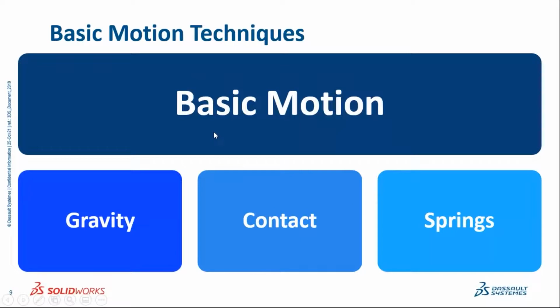Okay, so the second two points are springs and contacts. Just due to the time, we'll not be able to cover both of them, so we're just going to jump into contact. But just to know, springs can be made into basic motion. And I'm not just talking about modeling a spring or animating a spring as if it's compressing and decompressing. No, I'm talking about real physics, like a spring or a damper in a model, like a suspension kit, for example, where it simulates real spring motion.